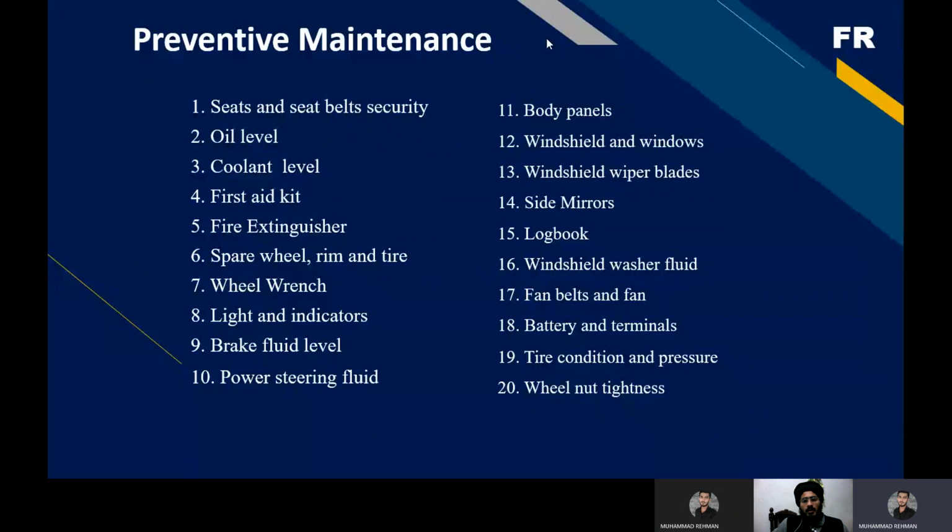And then comes the battery. Basically for the battery, you have to see that battery terminals are correctly connected, and there is no loose connection between them. And the level of water or acid in the battery, and the pH of the acid in the battery must be carefully monitored, and must be regularly checked by a technician after a month or two. Then is the tire condition. On a long drive, or you can also say on a short drive, you have to see the tire pressure and conditions, because if there is no technician nearby, you will be facing a problem.